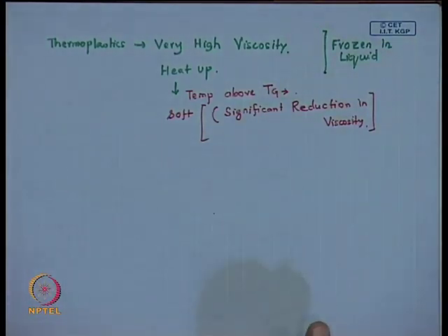If any one of you is interested, you are free to search the internet with keywords like glass transition temperature, thermoplastic, you can look at the chemical compositional details and things like that. But for the context of this particular course, I will be skipping all those details which I do not feel is that necessary. So, understanding this much, that a thermoplastic behaves more like a solid film at room temperature, and then once you heat it up beyond its glass transition temperature, it softens or behaves like a lower viscosity liquid, you can probably now understand how nano imprint lithography works.